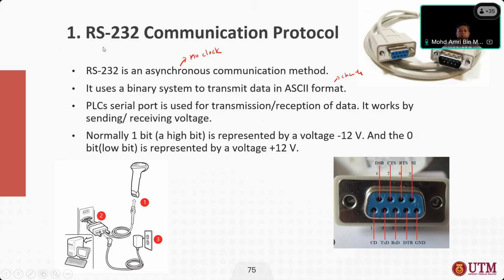For RS-232, I can give you an example: a device like a barcode reader. If you look at old PCs, they have the female port of the RS-232, but it has been deprecated and replaced with USB. It is still applied in devices in retail, for example a barcode scanner, but usually they have an RS-232 to USB converter if you want to connect this device to modern or the latest laptops nowadays.